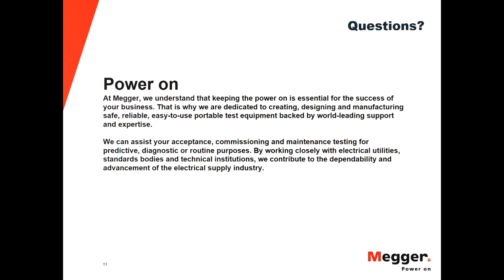The main interest of the ohmic testing is to determine the aging or the loss of capacity of the battery, or to correlate that in a certain way to the ohmic value. In nickel-cadmium batteries, that doesn't happen, and a nickel-cadmium battery definitely can show an increased ohmic value when it is out of capacity or when it's already a battery that is not good anymore.